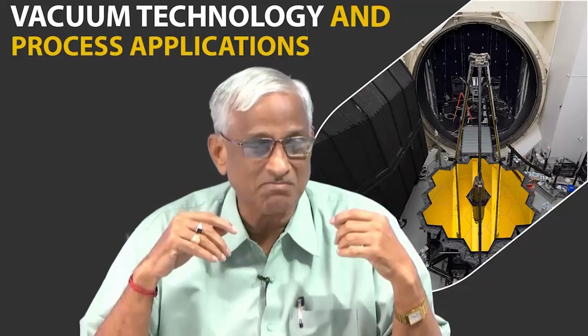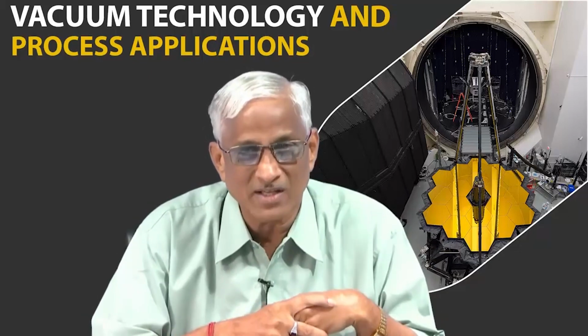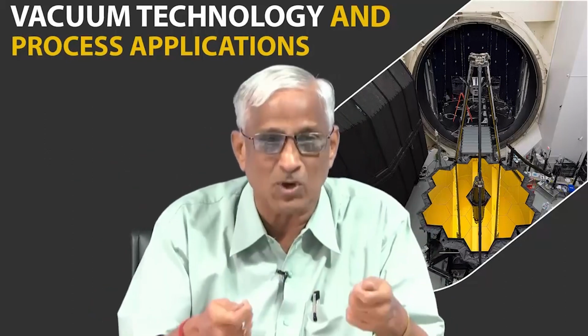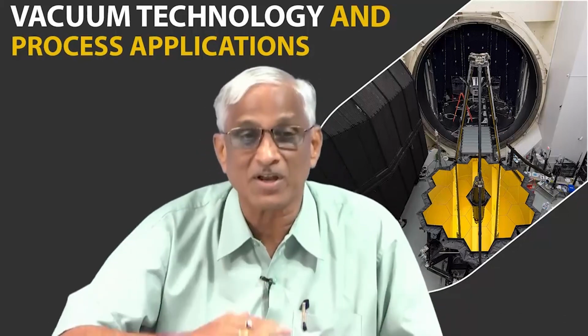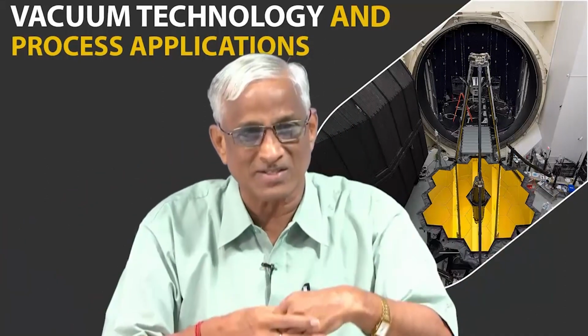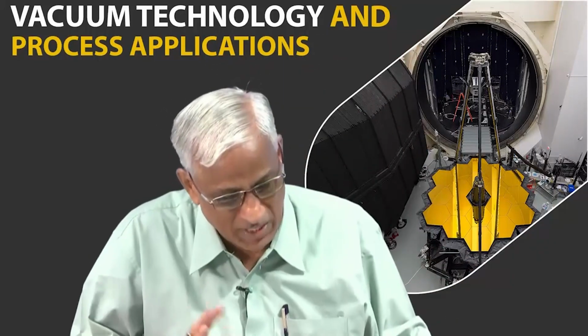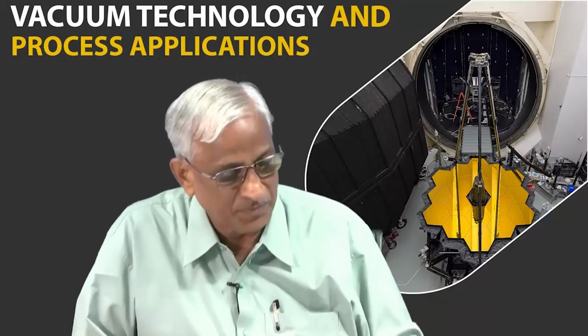If, unfortunately, a complete system suddenly develops lots of leaks here and there, then you may have to improve the welding in the next slot. Otherwise, this problem will persist forever. So, you have to improve your welding grade itself. There are some methods to check the welding on small plates, using advanced welding testing techniques. Then your company standard will go up further. Welding can be done like rough welding that we use in household applications. Welding should be done differently at high vacuum, and in a different style in ultra high vacuum. You should take care of all these things.